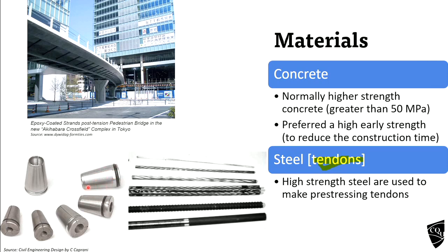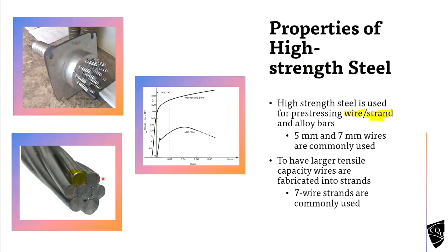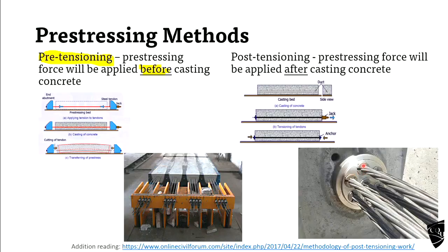So this is a wedge side. When you pull from the back side, the diameter will increase, so it's difficult, so it will tighten the wires. When you pull from the other end, the wedge tries to go inside, but the diameter is increased, so that will compress the steel wires that go through that. Okay, so this is how we put the connection in the post-tensioning.